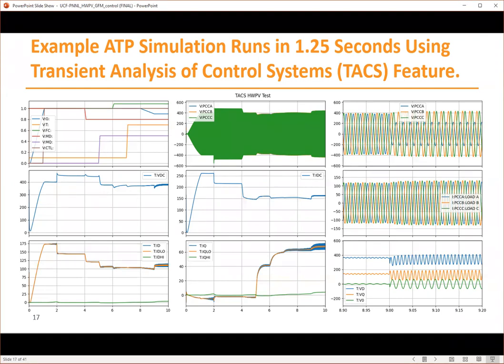But basically, in the interest of time, feel free to ask a question about it. Zoomed in on the 9 seconds, there's a single phase load transient indicator. You can see the voltage drops on phase A. The currents on phase A, B, and C increase slightly. And then you can see in the lower right, the D, Q, and 0 axis voltages have oscillatory components, either at 60 hertz or 120 hertz. Okay, next slide.